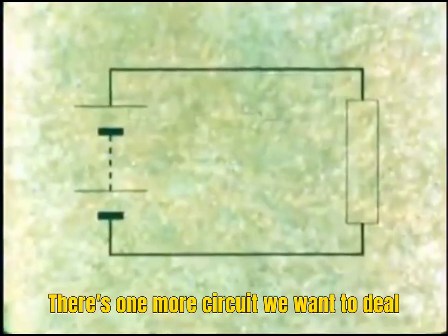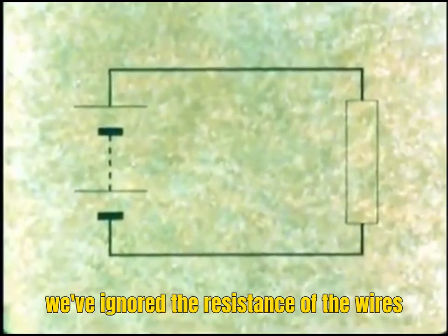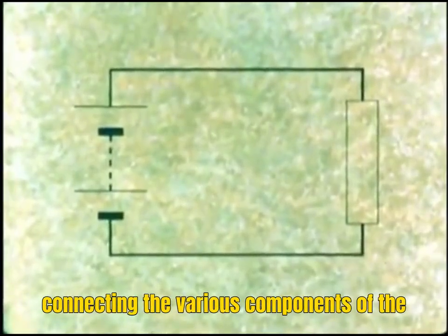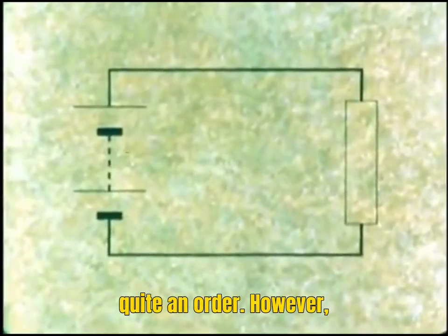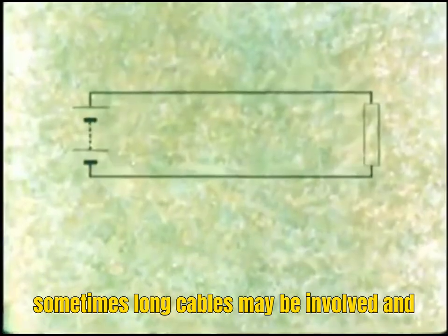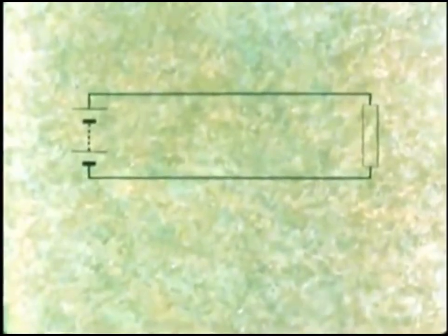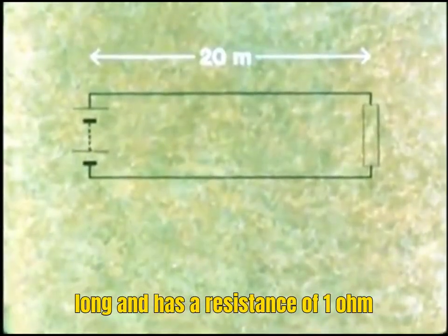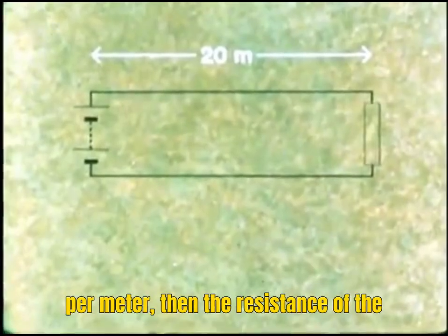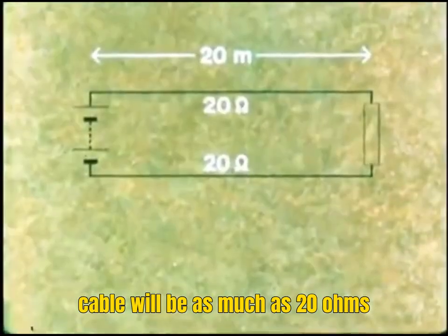There's one more circuit we want to deal with. In all circuits we've done so far, we've ignored the resistance of the wires connecting the various components of the circuit. This is often quite in order. However, sometimes long cables may be involved, and these may have considerable resistance, causing a voltage drop across them, which has to be taken into account. For example, if a cable is 20 meters long and has a resistance of 1 ohm per meter, then the resistance of the cable will be as much as 20 ohms each way.